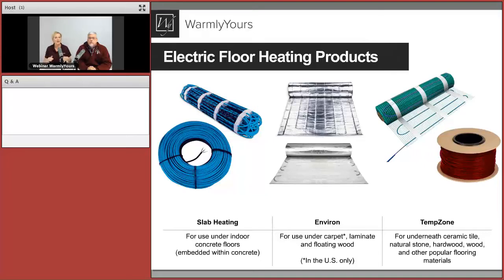And the reason for that is mats, almost like a blanket, cover a very large space very quickly. Just lay that rectangular mat down. The rolls provide the flexibility. You can roll those out. You can actually cut that aluminum, never the heating element. And you can then turn and design the area that you want it to fit. If you take a 6x10 Environ Easy Mat, you can literally install 60 square feet of floor heat in about 30 seconds. Boom. Because you just lay it out and run the cable over to the wall and you're done.